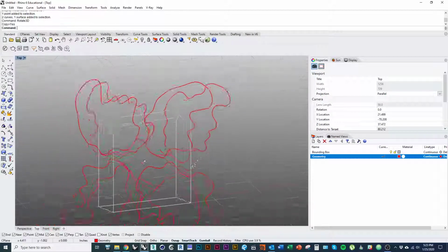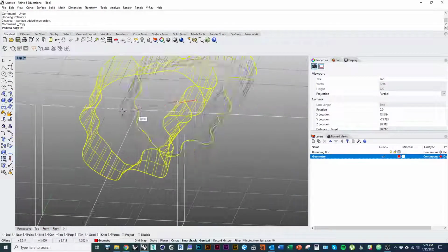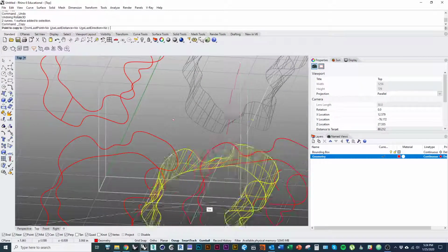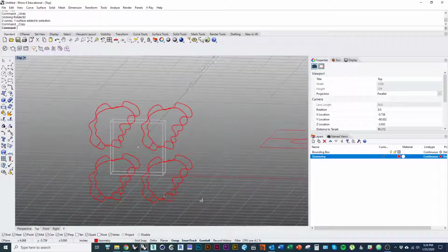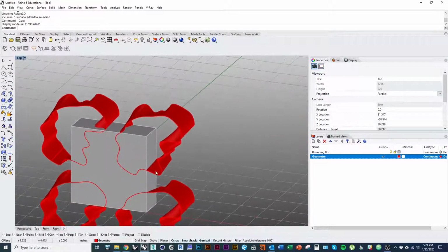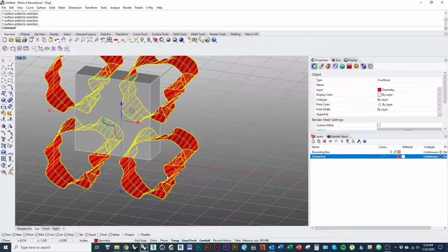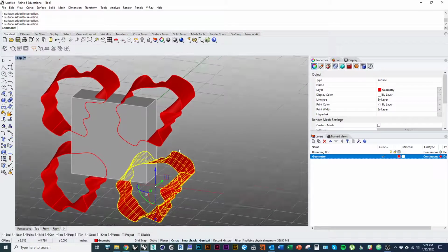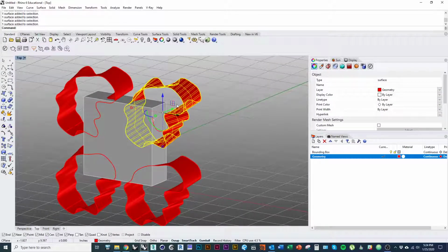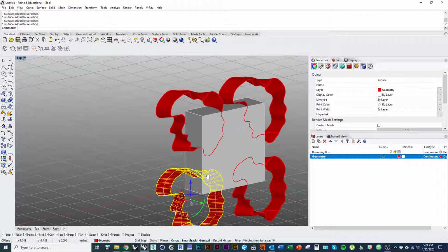4 times. The other thing that you could do, if you didn't want to try the rotation, would again just be to copy that same shape to each of the 4 corner points. And then once you've got your shapes set up like that, what I like to do is just do a kind of Boolean operation, because it should be the quickest and cleanest. Again, this will only work if you have a closed set of geometries. It'll only work if this surface is going all the way through.